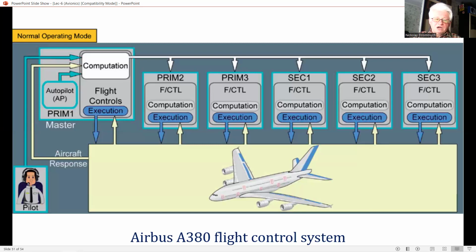Progressive control law reconfigurations occur as a function of the system failure status and are indicated to the pilot through the following laws. Normal law, in which auto trim control laws and flight domain protections are available.